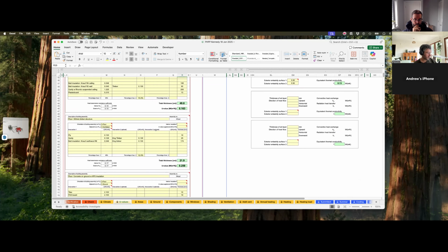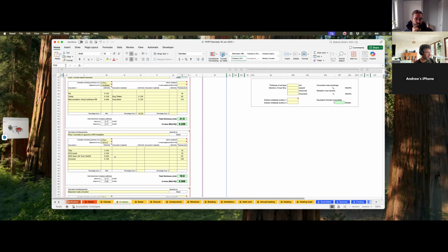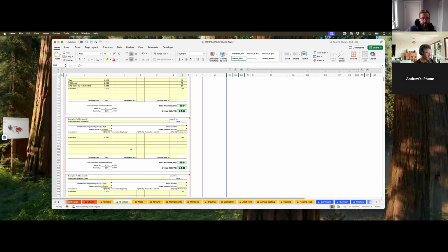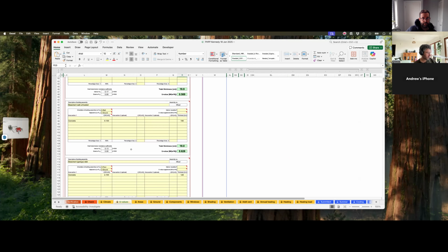Now your floor. So you've got the concrete on ground. So the concrete slab I'll put in as a 120 mil slab. 50 mils of a very specific XPS foam. Fibre cement sheet board and then your tiles. And the reason for the fibre cement board, remember, was what Harley mentioned, that when you want to retile in 20 years or 30 years, you don't have to pull the insulation out.